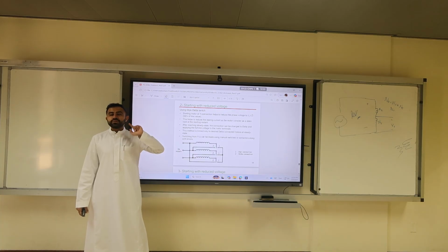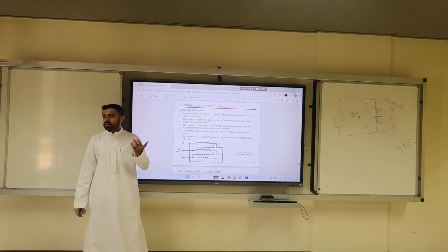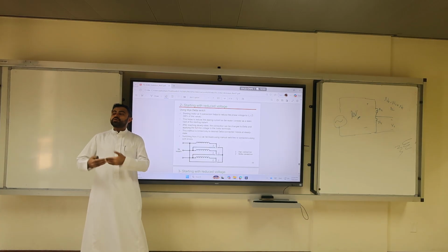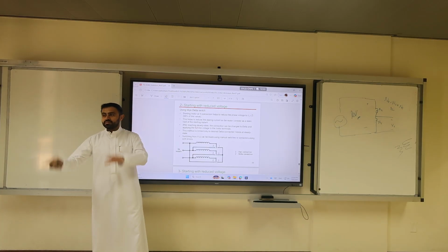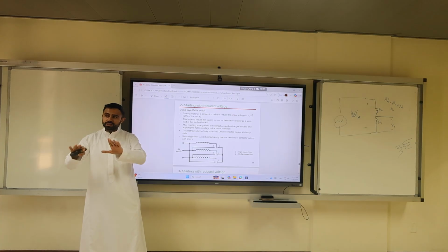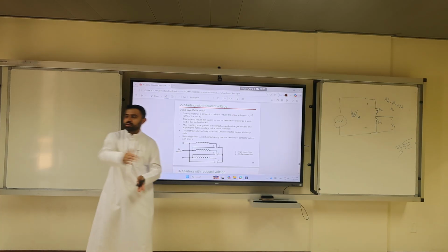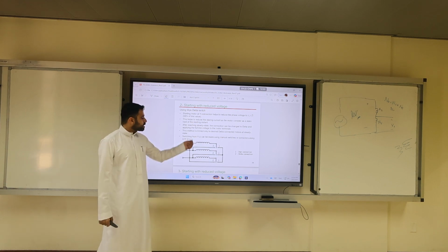Can you use it if you plan to use the motor in the Y connection? No. If you already plan for your motor to operate in delta, you may start it as Y, and then switch to delta using this switch.